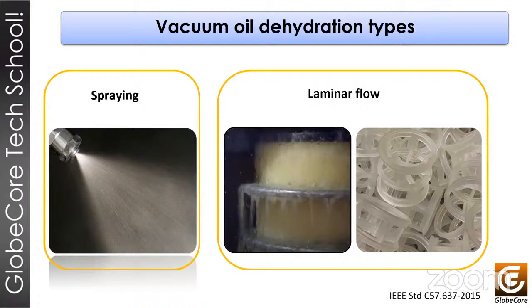We have really high versatility, and the versatility can be seen in the open-ended designs, which provide highly efficient use of the surface area in the rings. Also, there is low resistance to liquid and vapor distribution, and we have mechanical strength. The internal transverse structure of the diameter spokes makes the nozzle mechanically strong and suitable for use on deep columns.